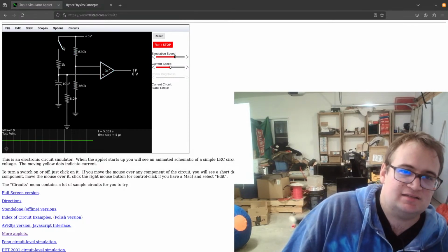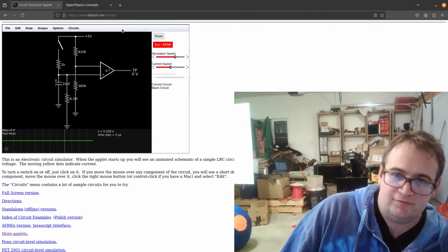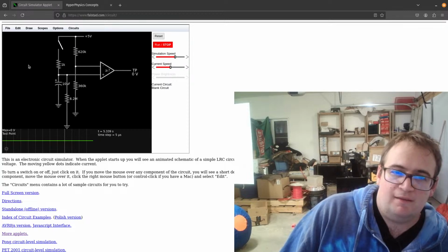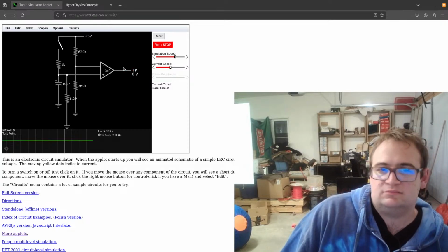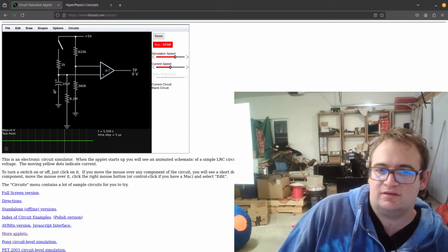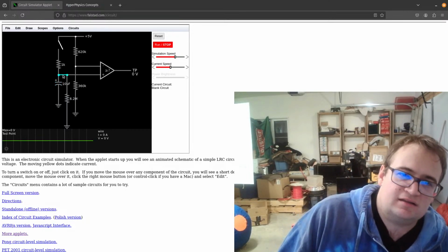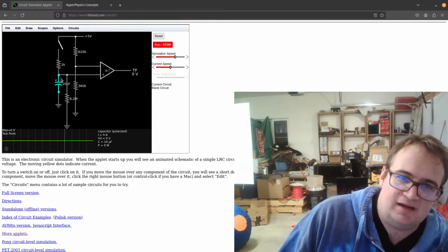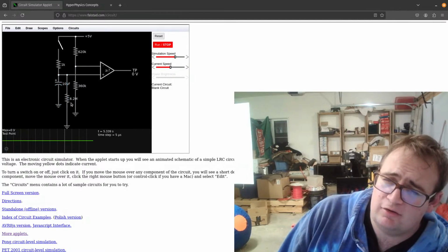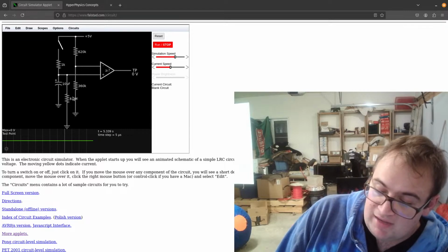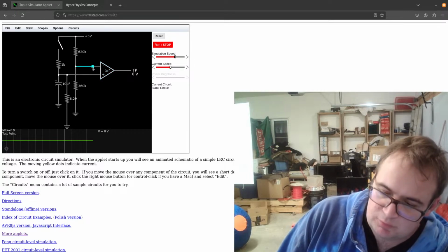But when we flick this, this capacitor is going to slowly charge up to the full 5 volts. And then this will output 5 volts for the time that it takes this capacitor. Yeah, I wanted 10 microfarads there. So when this capacitor charges up to 5 volts, it's going to discharge itself through this megaohm resistor, and eventually it will go below the voltage at this point.